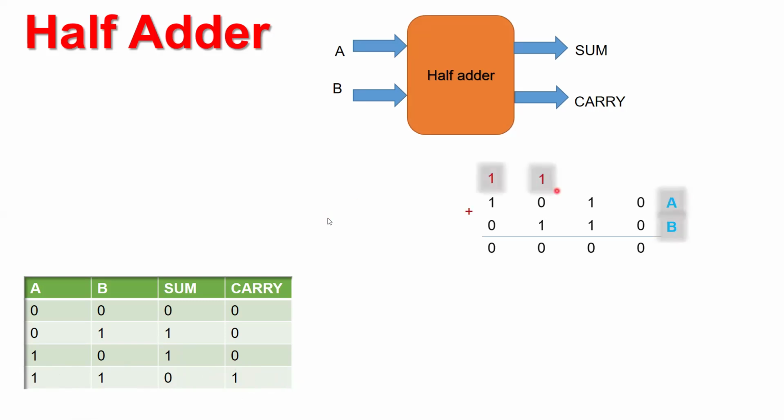So for example, let's say you have A and B, which are 4-bit numbers each. This is 1, 2, 3, 4, the LSB, least significant bit, in number A, and this one is the most significant bit. For B also, this is the LSB, and this one is the MSB. Now we start the addition of individual bits, starting with 0, 0. Both A and B have the values of logic 0. The binary addition here gives sum equal to 0. Obviously, there is no carry.